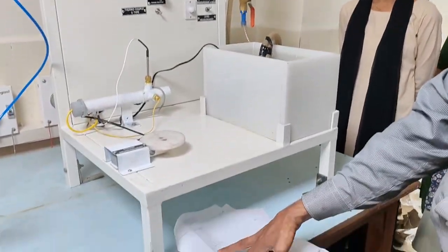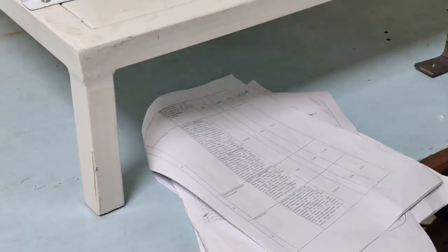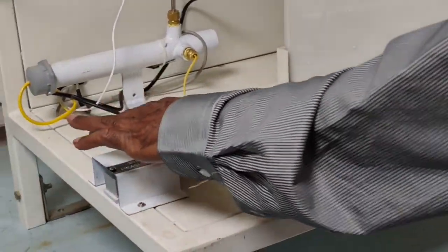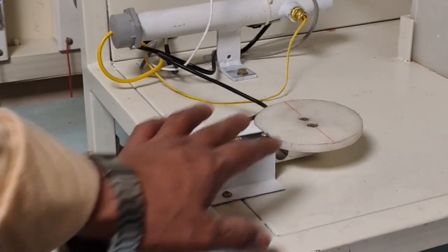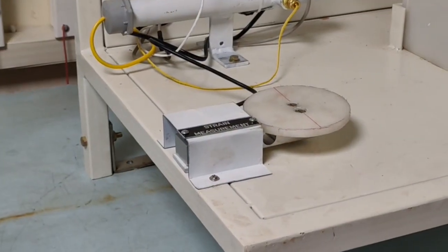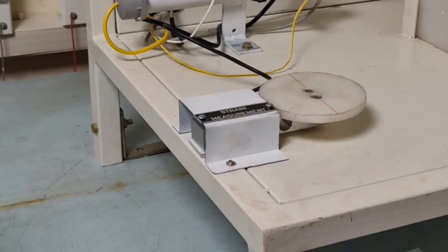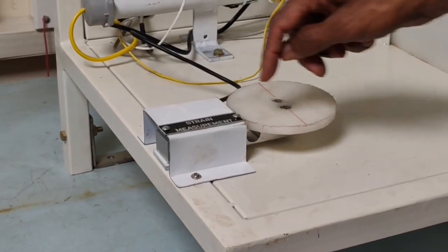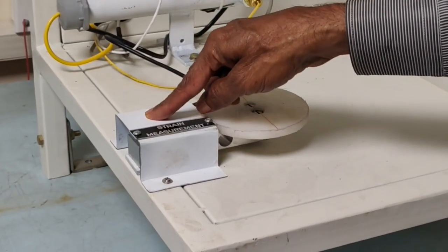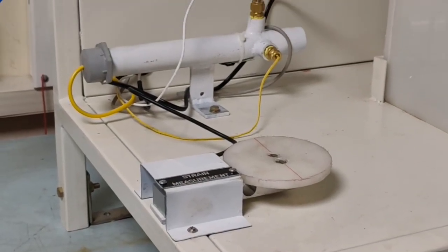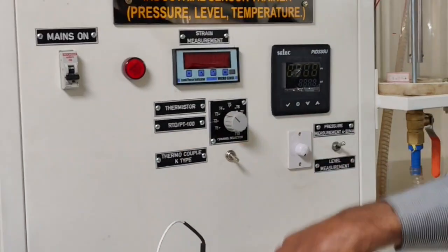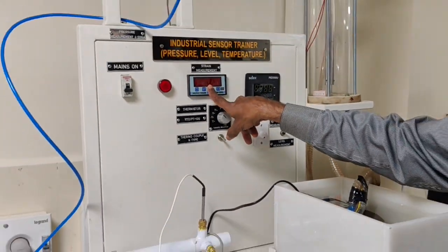That is regarding the 3 temperature sensors, pressure and capacitive. One more is there, strain measurement. This is the strain measuring system, one more sensor. Once you put a certain weight, the material is subjected to load. If you press and put weight, it is subjected to strain. The output from the strain will again be in millivolts. That millivolts will be read in a separate indicator. These 3 use a common indicator. For strain measurement, it is a different indicator.